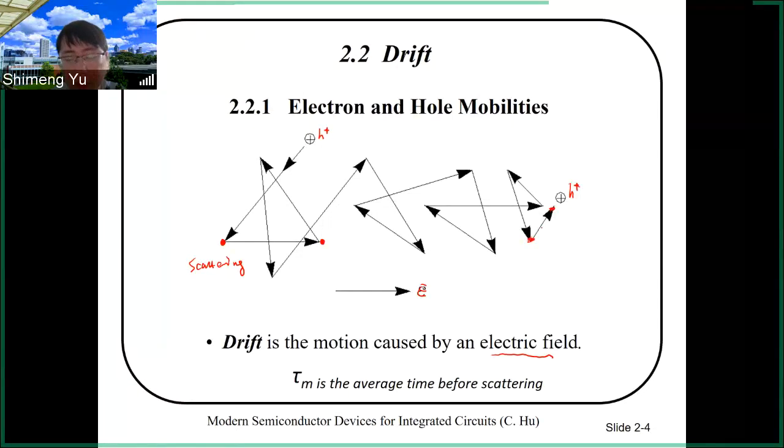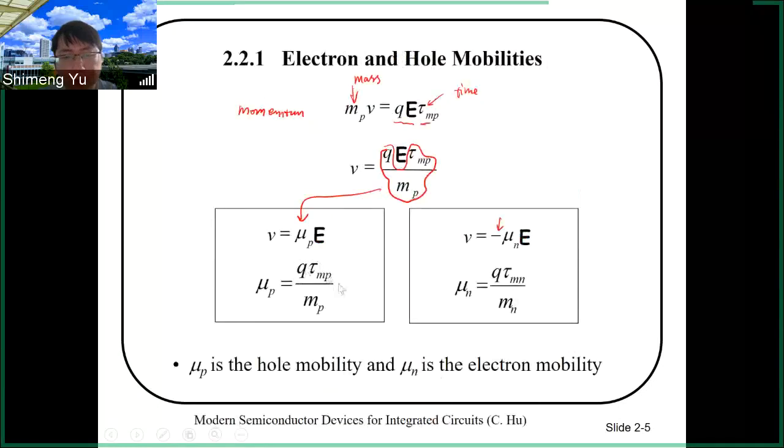So the mobility will be lower. If you go back to the origin of this problem, that is how you explain the mobility decrease with higher doping: more frequent scattering, and the time between those scatterings decreases. That's how you see it in this mobility equation.